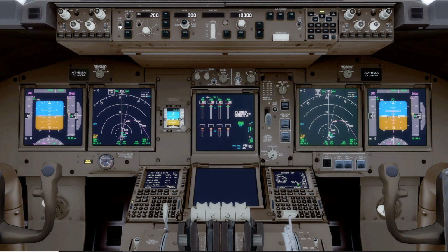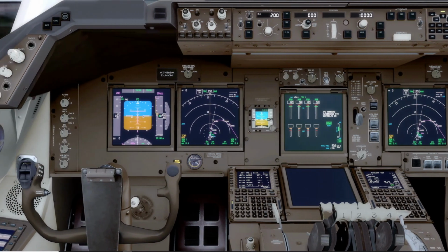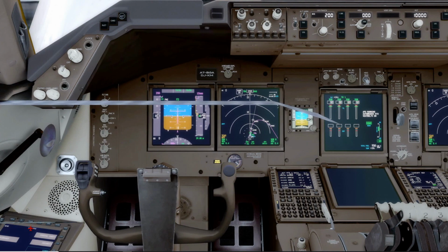Then we do the MCP, flight director on, auto throttle arm. The heading select indicators in auto, and the disengage bar is flush and not pulled down. And then we stop right there because it's what the FO did over here. We can then come down to our side panel, and we can do the oxygen check just like the FO did down here.